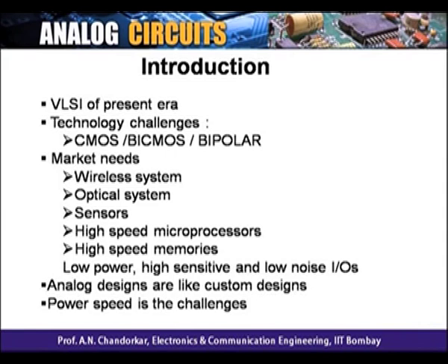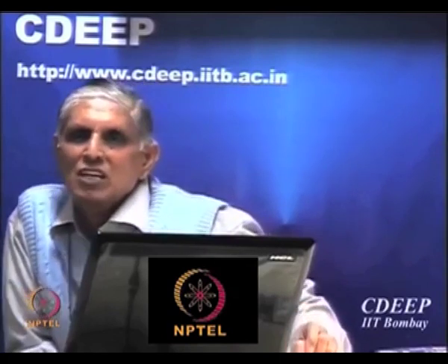The word VLSI has come from very large scale integrated circuits, since the 60s when the semiconductor chips started coming into the market, particularly from Bell Labs and then from Texas Instruments. We started counting the number of transistors per chip. So we say okay, 100 is small scale, 1000 maybe medium scale, 10,000 and above large scale, and maybe millions very large scale. So that's the number we are talking.